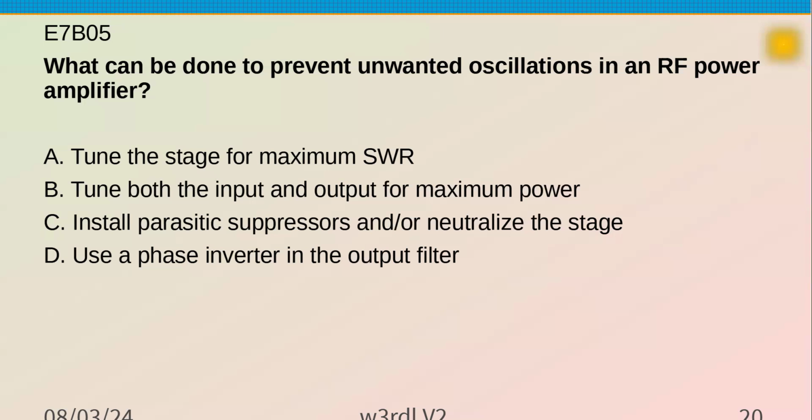It reduces the gain. It doesn't add to it. It also will be feeding back all harmonics too. So you're going to reduce the gain and flatten the response curve. Well, yeah, I mean, you don't get something for nothing.